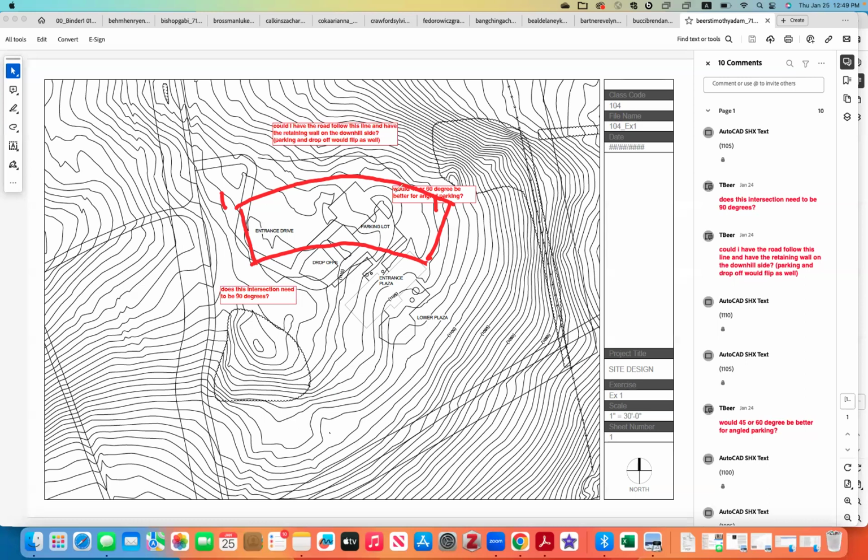So the turnaround, we would suggest for that to be toward your building. So that becomes a drop off and a turnaround area. What I would recommend would be for you to measure and make a not angled, a 90-degree angle first and see how much space you need. And then you can decide how much I need to rotate to fit them in.